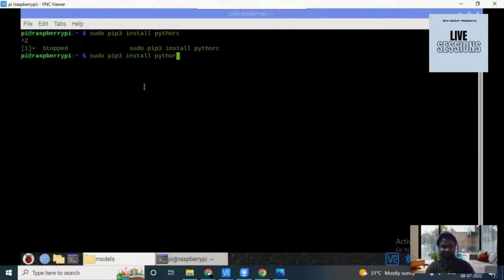But you can follow these commands, like sudo apt install, sudo pip install dlib and OpenCV for getting the camera interface of the Raspberry Pi, tracing the camera with the Raspberry Pi, and getting the video of that. And after a lot of that, TensorFlow, to get TensorFlow installed on the Raspberry Pi, and then after getting all these things installed, you need to clone the modules of the object detection module. You find it on the internet.